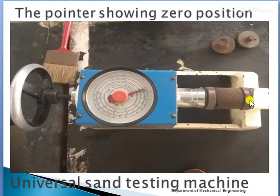These are the two pads, the black ones, the compression pads, which are flat in nature. For compression strength, you place the sand specimen in between them and hold it. Slowly you start rotating this wheel, and here you see the threaded shaft. When you start applying the compressive force on the specimen, the forces start applying, and in this pressure gauge we start getting the reading.